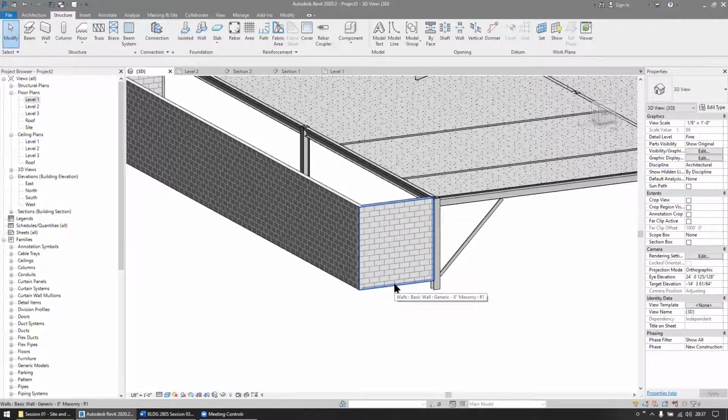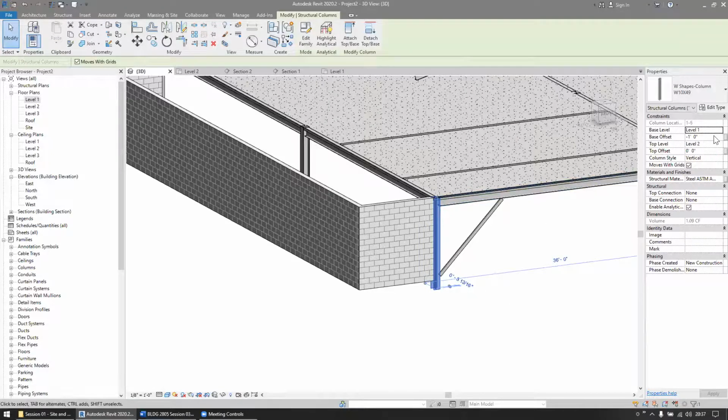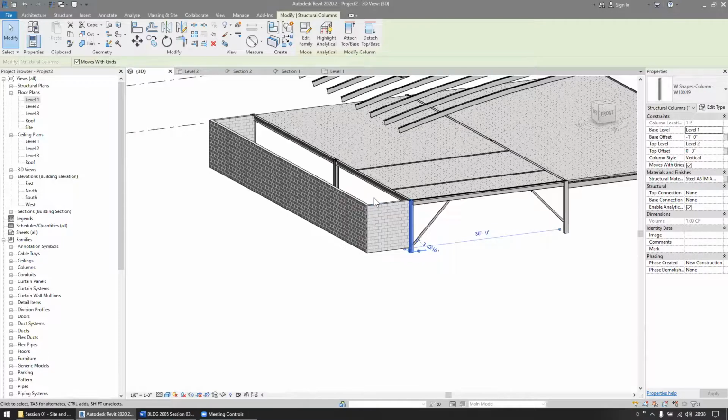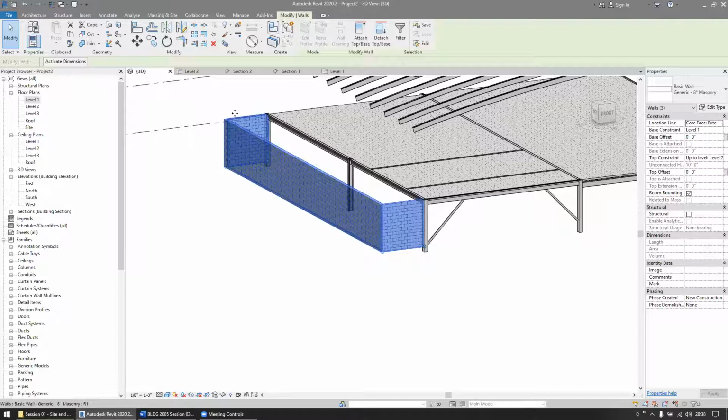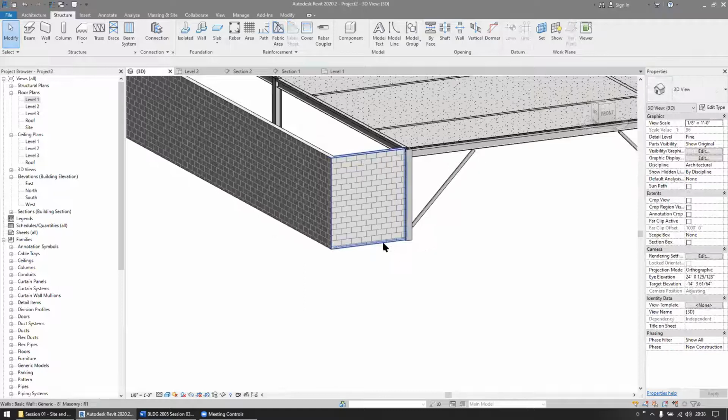Now, keep in mind we've got some columns here that go down to 1 foot below our floor line, because typically with our steel columns, they don't just go down to the floor. They usually go down another foot below, so they can just put it right on top of the footing. So we might then also take our masonry or concrete walls and set them down an extra foot as well. So both of them will have footings at the same elevation.